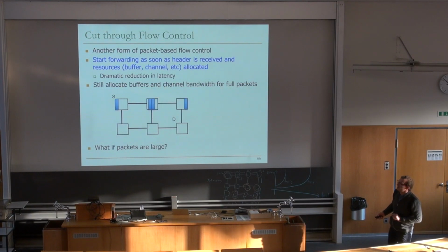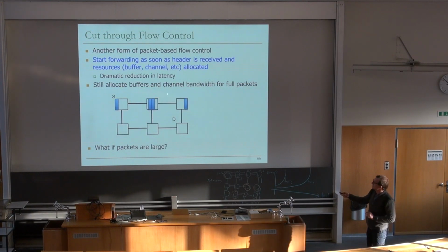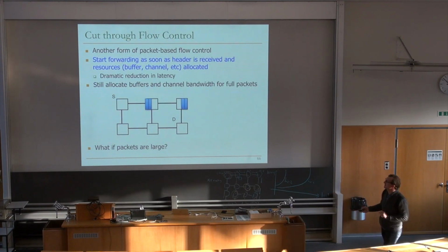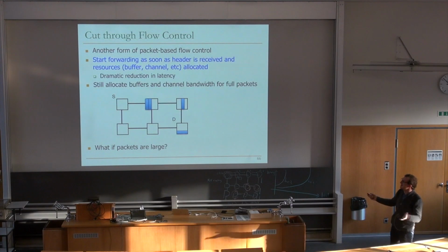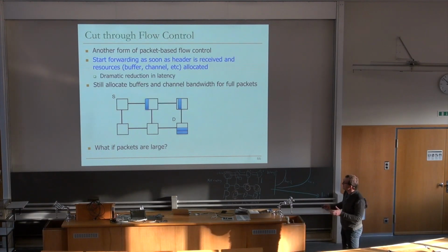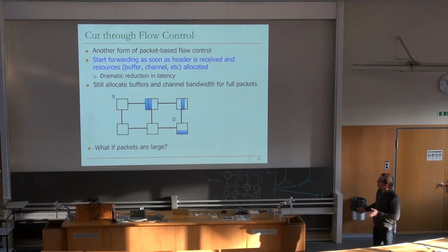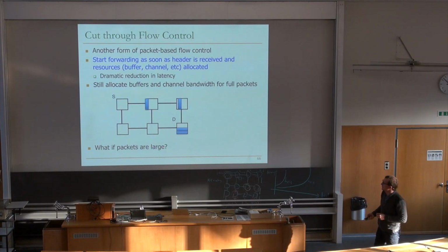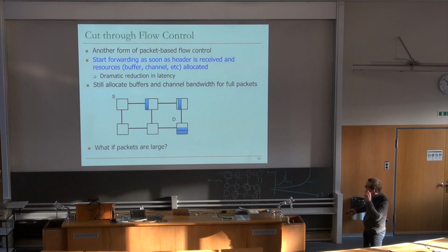And now the packet is distributed across routers, right? The header can go before the full packet is received. And the body and tail are in different places. So you can see that the header is everywhere. Well, now the packet can be distributed across the network. So this is good because your latency is reduced, the header is received very quickly, and the packet is overall received well. The tail is received late, of course, but there's a large reduction in latency.